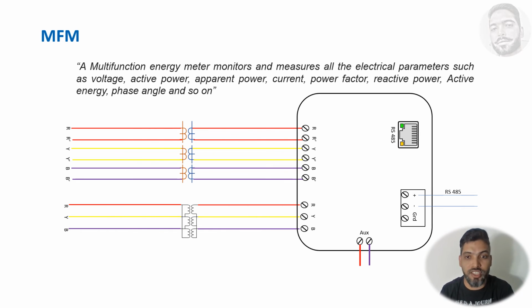Never connect this ground signal to your electrical ground. It will be the worst thing in your life if you put it in your earthing. Don't put it in the earthing. That signal is just the shielding of the cable. You will find a metal net-type thing on the upper side covering your communication cable, and that you have to put on this ground.